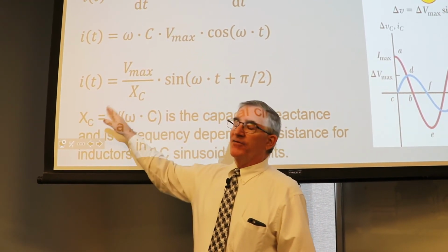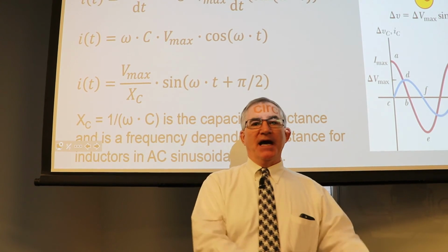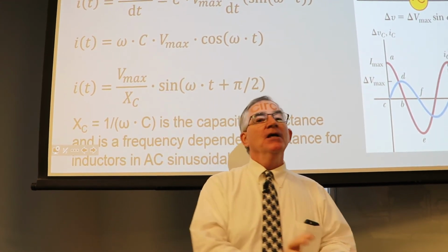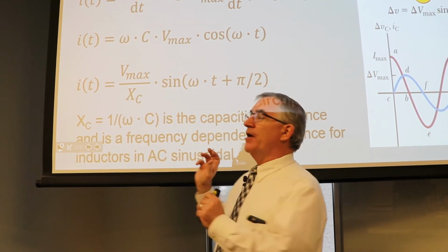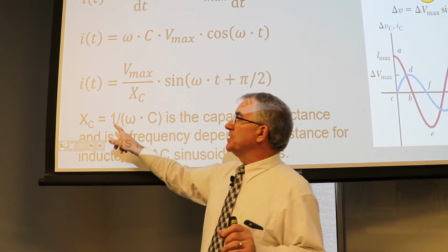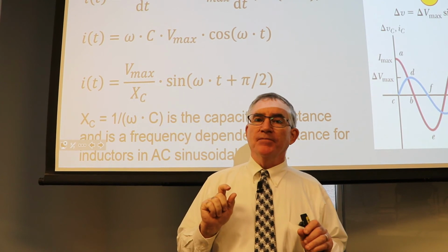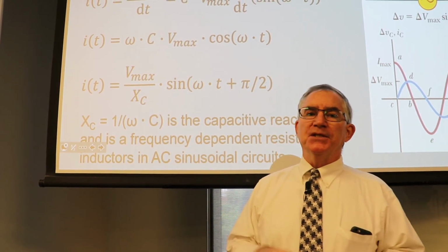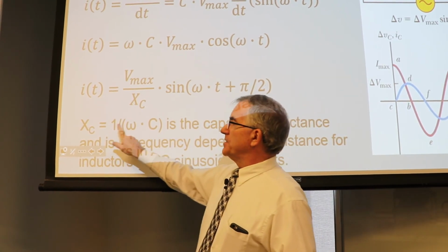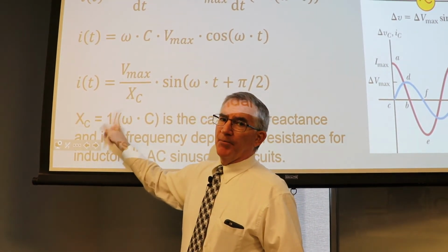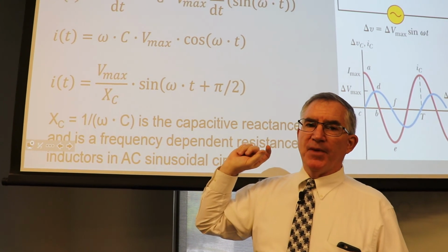And so the effect of the capacitor in shutting down the circuit, remember a fully charged up capacitor is an open circuit. But if there isn't enough time to charge up the plates because the signal is so fast, then the resistance of the capacitor is low. So that's why the omega is down in the bottom. So as omega goes up, the resistance of the capacitor goes down.